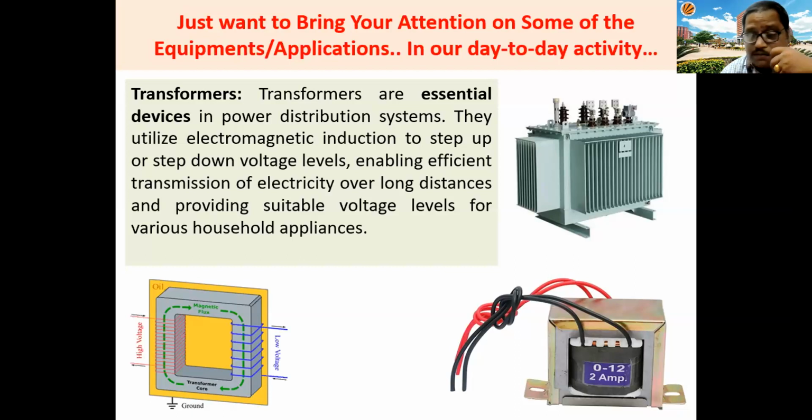There is one more kind of EMF, which we call dynamically induced EMF or dynamic EMF, which we have in the case of rotating electrical machines. A transformer comes in the category of static electric machines. Things are stationary here. In this transformer, we don't have moving components. Here the flux is changing. In rotating machines, there is some component which is stationary and some component which is rotating. In a transformer, we don't have any rotating component. Flux is changing here.